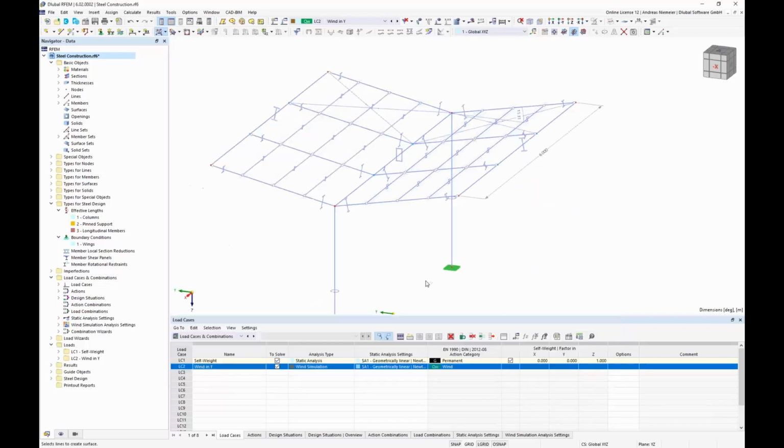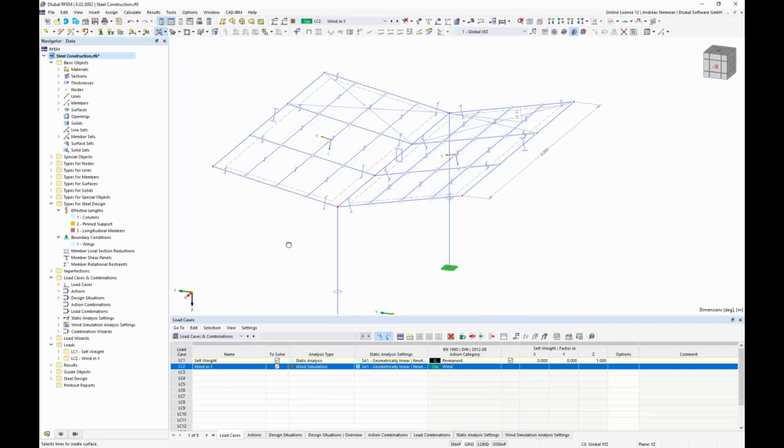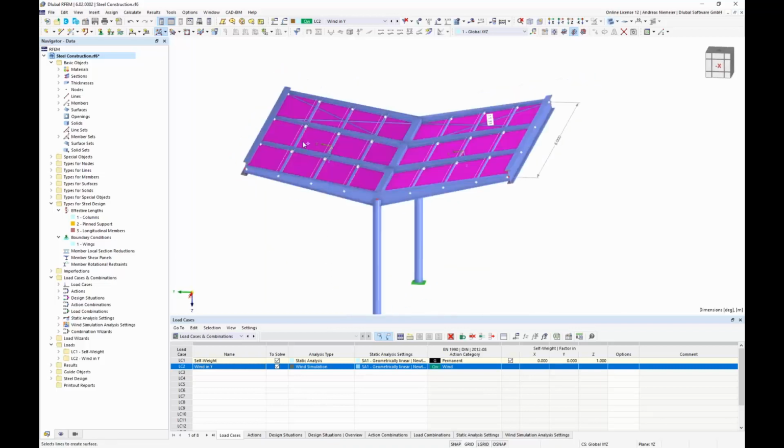So let's select these boundaries and place the surface inside. Of course the program will delete the results, but this is quite regular here. So now when we turn on rendering, you see we have this surface inside, and we can go ahead with our wind calculation.